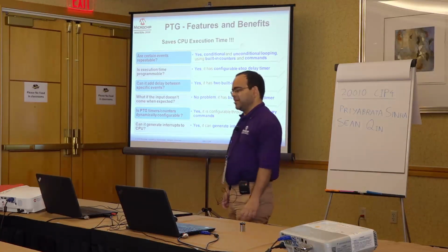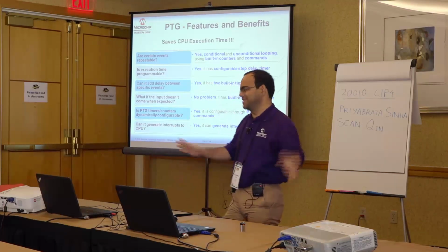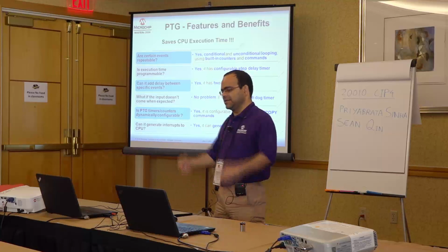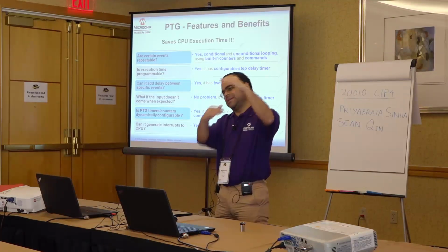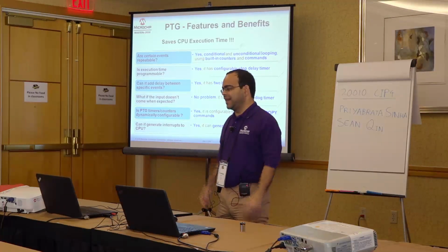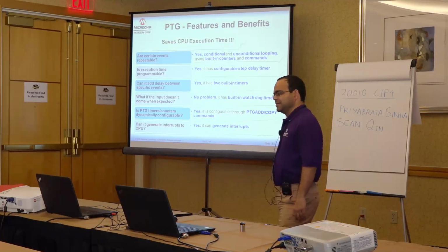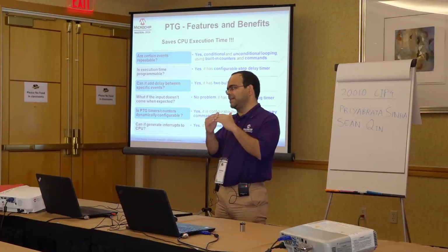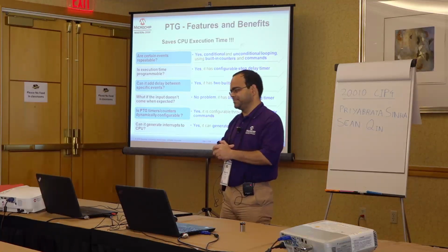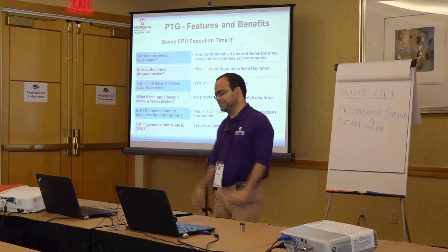The next thing you might wonder is whether the execution time is programmable. By execution time, I do not mean the execution time of the CPU, which is obviously determined by the clock speed of the device, but how frequently the steps get executed. Once step 0 has executed, when will the next step be executed, and so on. That is configurable, and you can change it on the fly as well, because there is something called a step delay timer. By configuring and enabling the step delay timer, you can insert a delay between successive PTG steps, so you can exactly control how frequently these PTG step commands get executed.